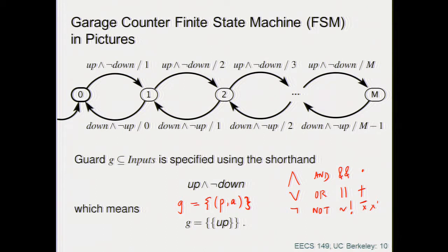Sometimes there are cases in which it's convenient to represent the state as an output. Now, is there only one way of describing a state? No. You have choices. But the most important thing is that, if you remember from ordinary differential equations and linear system theory, a state is essentially a summary of whatever has happened to the system before.